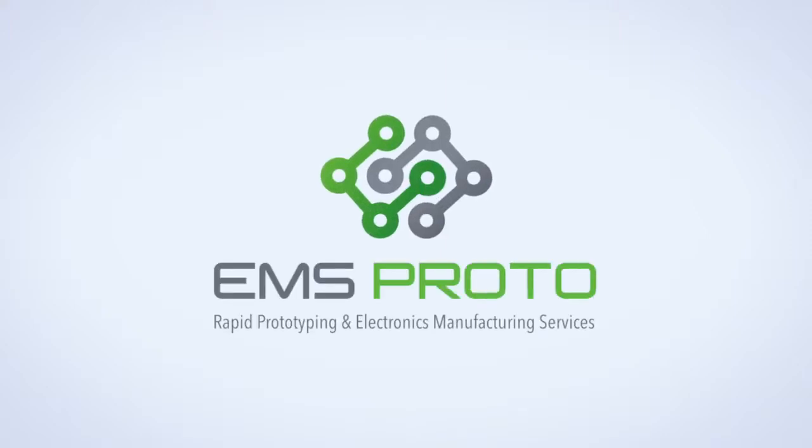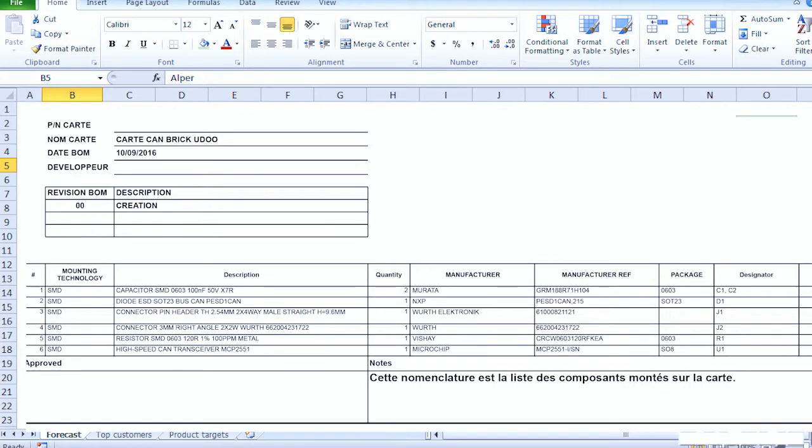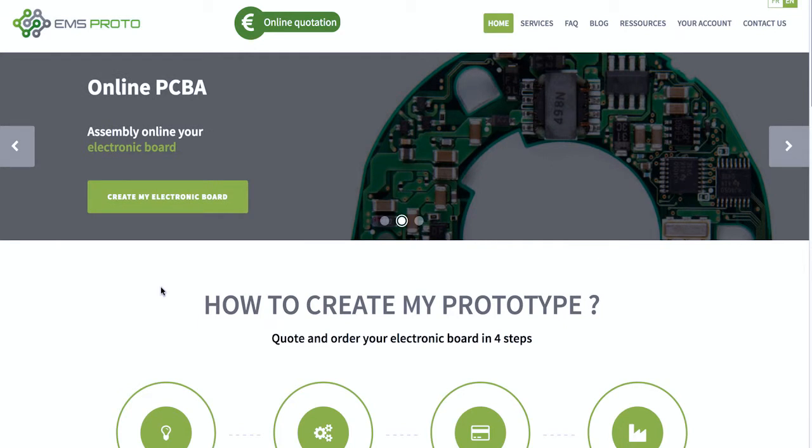EMS Proto's website allows you to easily and quickly quote the cost of components, PCBs and assembly labour of any electronics boards. In order to do this, you need to upload your bill of materials. It has to contain at least the component's quantity per board, the manufacturer or supplier's references, as well as the reference designator of your components. Once on the emsproto.com website, click on Online Quotation.